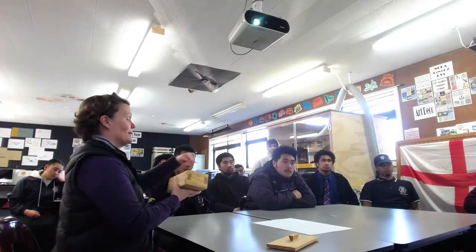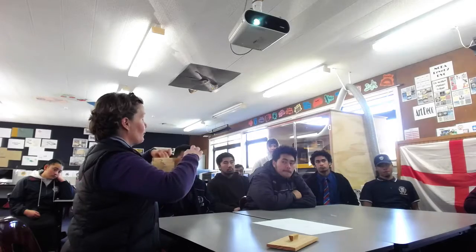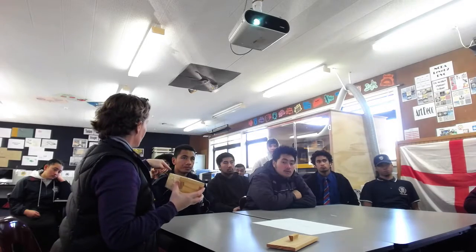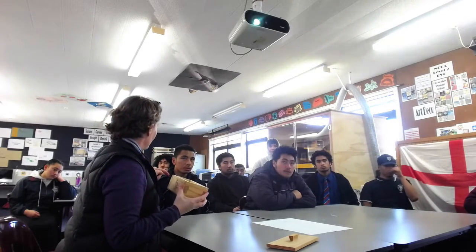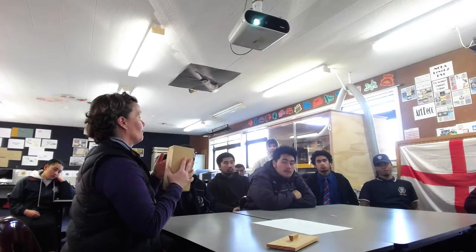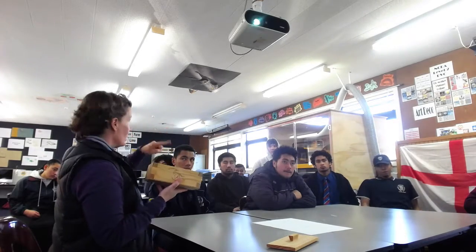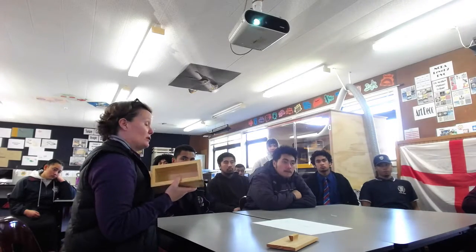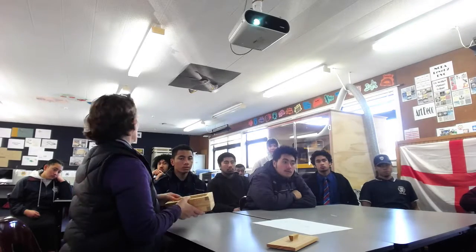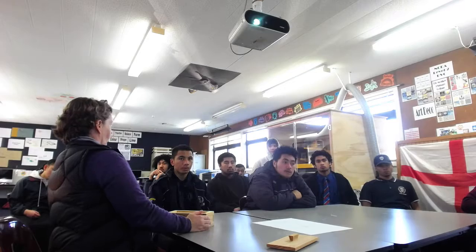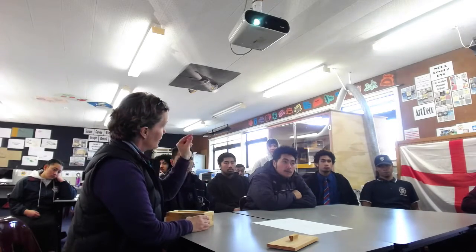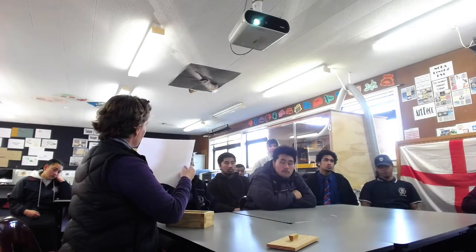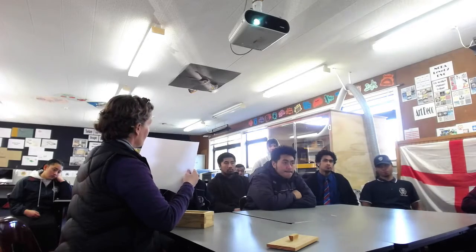Two different pieces of material, that piece and that piece, are two different pieces of material. So you'll see on the drawing, the lines are going in different directions to indicate that it's not the same piece of material. If this was made out of a solid cast piece of plastic, all the same material, then those cross-hatching lines would all be the same, in the same direction. And then the cross-hatching on this small bit here, because we've only got two choices of direction, they can go that way or they can go that way. When you need another choice, you make your lines closer together. So the drawing for that one's just here. These lines here are closer together.